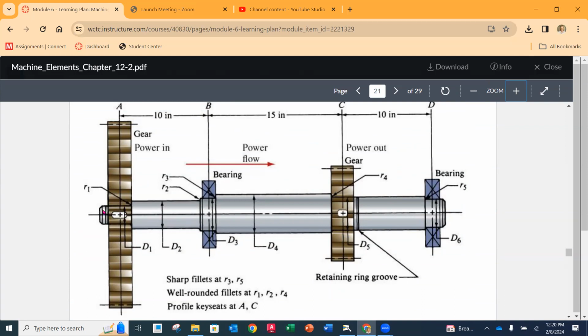The next thing is, on the left-hand side, we've got a retaining ring, all right? We have to have that identified and known. And then on the right-hand side, we've got a shoulder. So to locate this so that it doesn't move around, we're going to push it up against that shoulder. And on the other side, we're going to put a retaining ring.